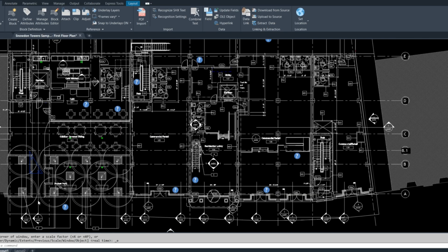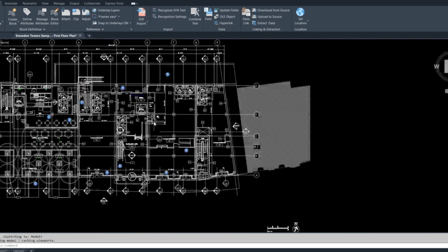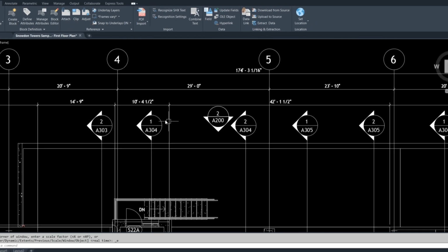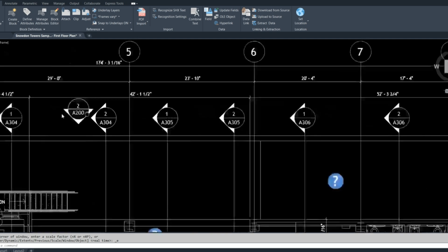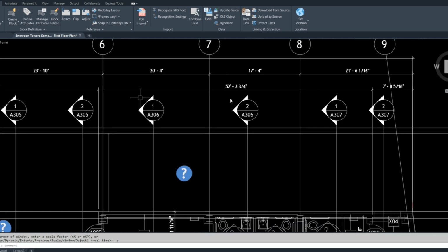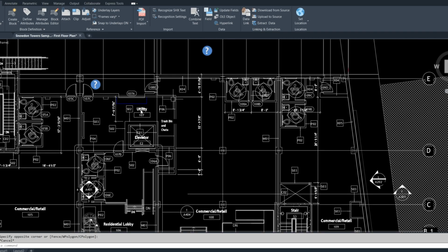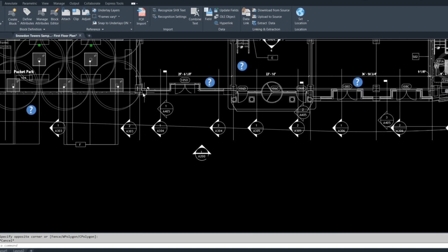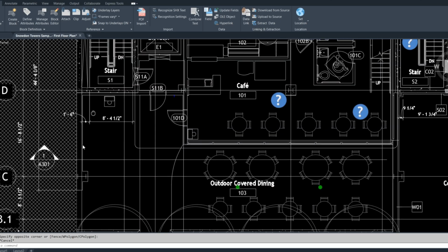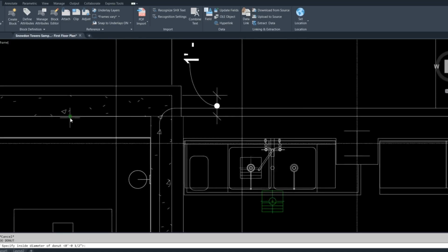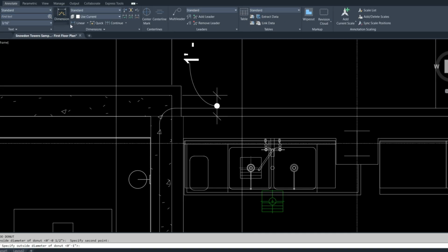In the plan, we can pick any one wall or grid line and scale from that particular spot, so we have to search for specific portions in the plan. Finally, we found a round figure to make in the meters portion. It's showing 1 foot is equal to 0.3048 m. So now we can scale the plan, picking up this area.